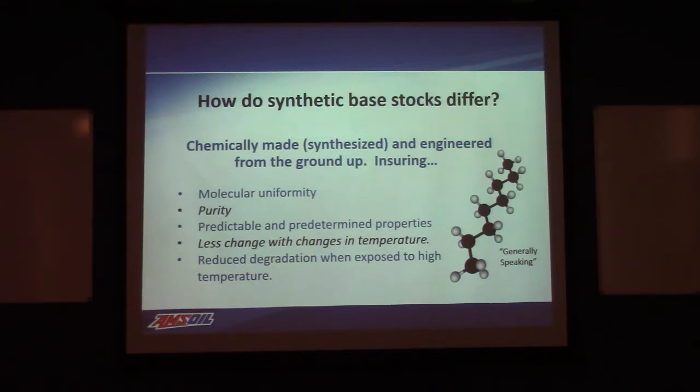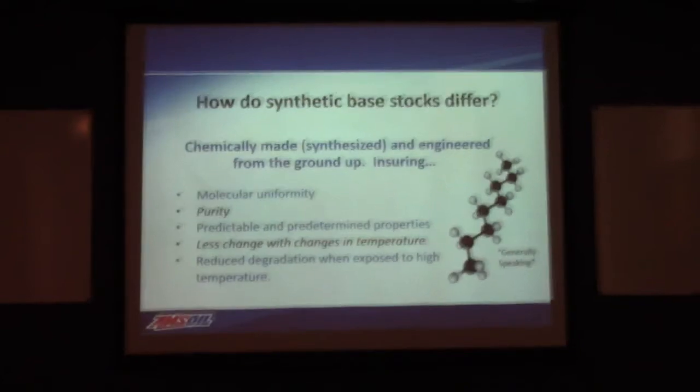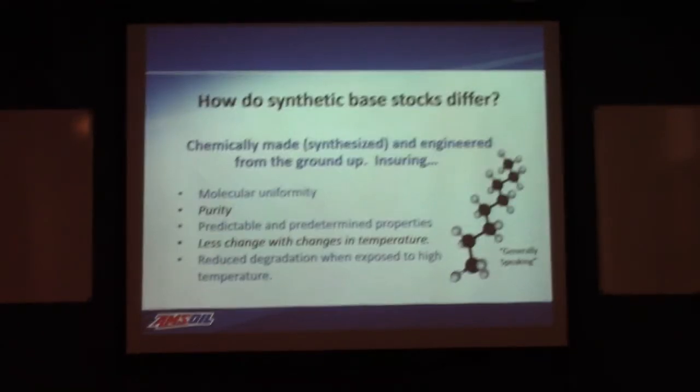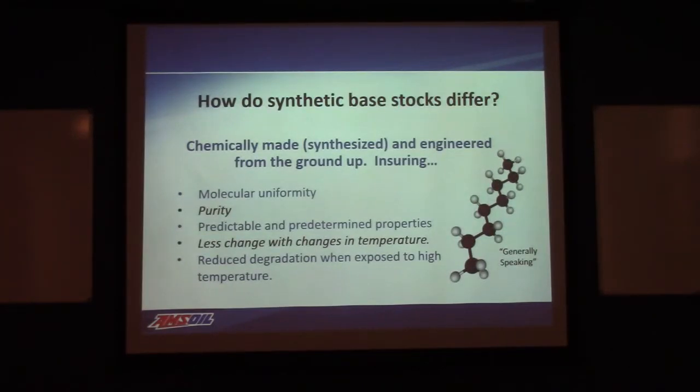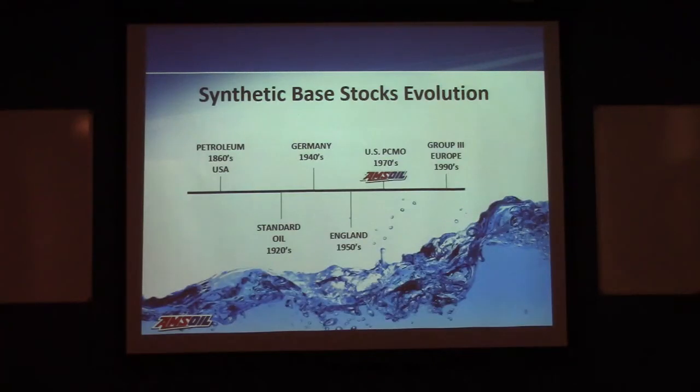They reduce degradation when exposed to elevated temperatures. Synthetics will not break down as fast, as rapidly, when exposed to these high temperature environments, especially the ones we're seeing now in today's automotive technology. So they're less self-contaminating, they can last and do their job for a longer period of time in more severe type environments. So a lot of pluses all the way around on it.